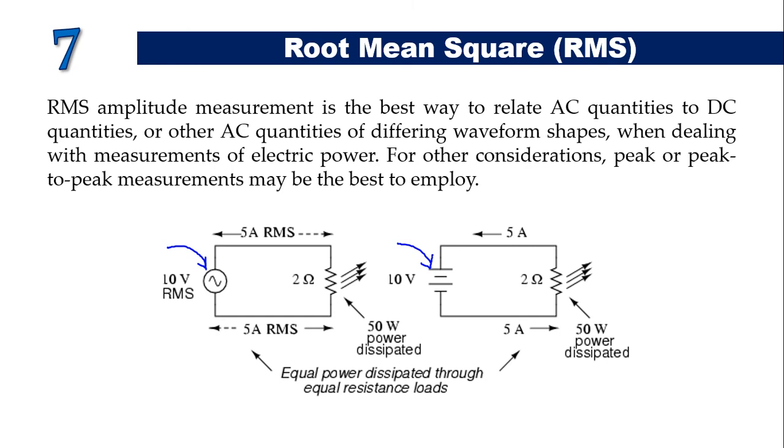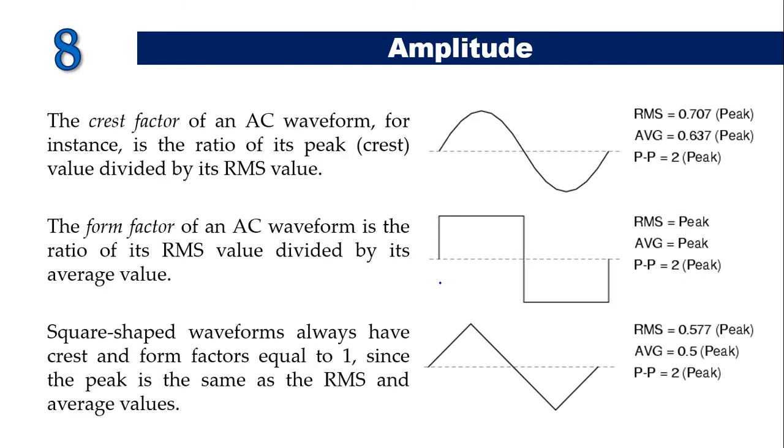However, when rating insulators for service in high voltage AC applications, peak voltage is most appropriate, because the principal concern for insulators is flashover caused by a momentary spike of voltage, irrespective of time. So, that's all it is.